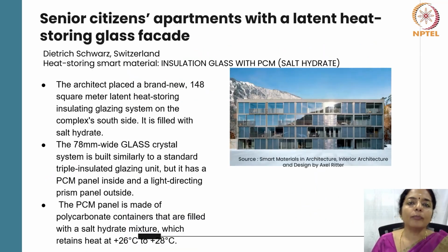Now we will look at a small case study of a senior citizen's apartment with a latent heat storing glass facade in Switzerland. The Swiss architect Dietrich Schwarz has shown in several of his buildings how, in addition to their latent heat storing properties, the ability of PCMs to change their optical appearance can also be used in a facade.